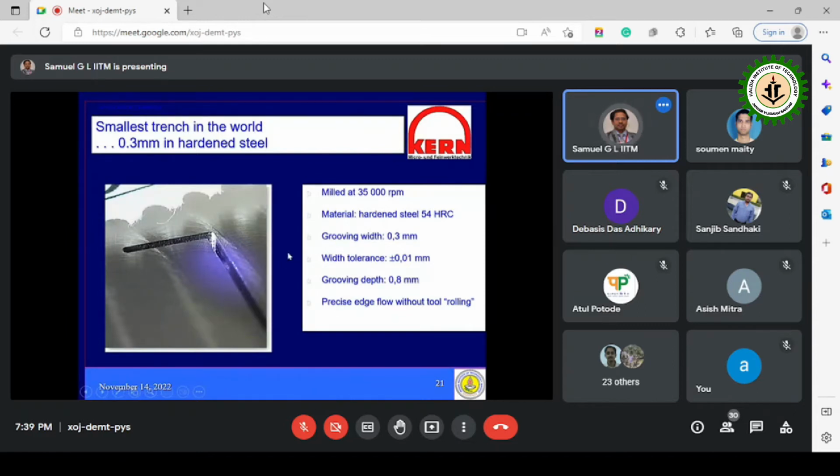And also there are trenches or micro channels with a high depth by using which we can make microfluidic devices. If you look at the product being used for detecting coronavirus, they had a portable kit. I think in the second wave and later, many of them never wanted to go to hospital, but wanted to test themselves. So they had these kinds of kits. They are called microfluidic devices, where there are micro channels and micro chambers in which the tests were conducted.